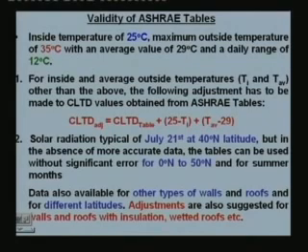Okay. So if you look at the ASHRAE handbooks or other air conditioning handbooks, all these tables are given, either CLTD tables. If you look at other handbooks, they give what is known as effective temperature difference tables, as a function of the type of the wall, orientation, solar time, and all that for fixed conditions. And they also suggest adjustments for other conditions. Okay, so if you have the tables and your specific conditions, then you can get the tabular value, apply the adjustment, and get the adjusted value of CLTD or ETD. Okay, that one must use for calculating the heat transfer rate.